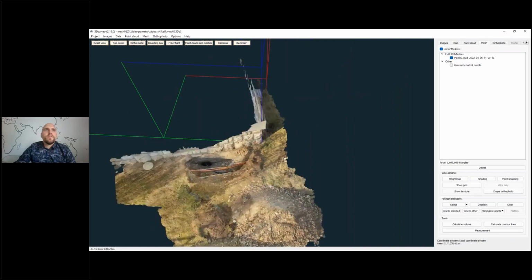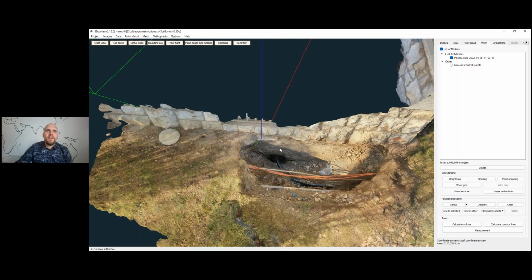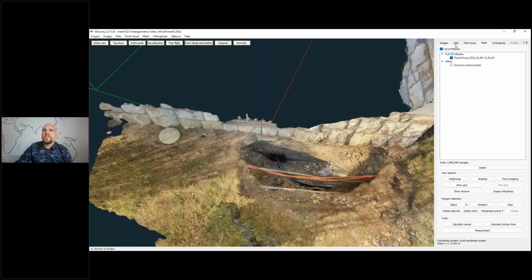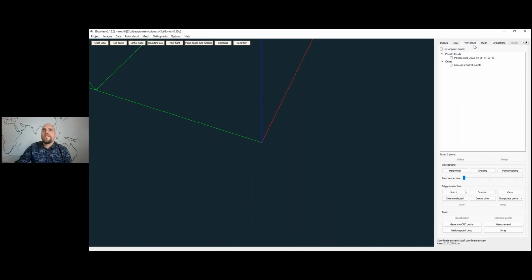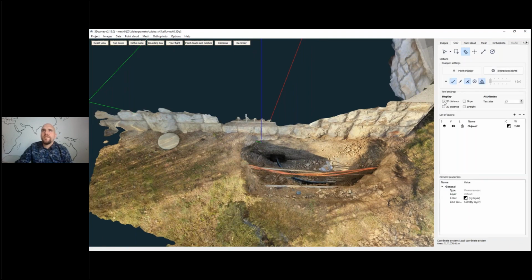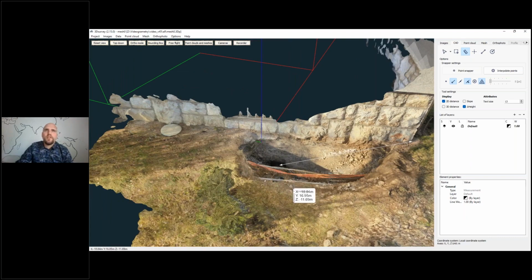Okay, so now here you see this. This was the excavated site because we had some water pipe leakage, so the water pipe had to be located. In our case, they looked at where the water pipe is going into the building, and then they excavated this area. Now with this kind of data, if we would need to find it in future, we could just measure now here. I'll turn on the point cloud. Now we could just measure and go to CAT measurement. So now it'd be interesting 2D distance and there the height. And we could say from this edge here, go 2.4 meters to the left and 1 meter down. And there will be the pipe coming into the building.